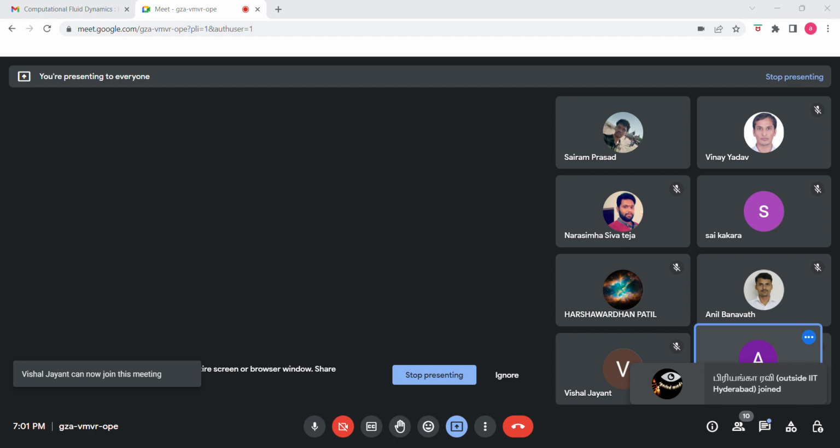Generating non-uniform grids is also not always required. But what is required is to generate an optimal grid that should be a proper compromise between accuracy and solution cost. We should see what we require in certain problems, and based on that we design a proper grid size. That is, in the discretization scheme, we go for delta x, right? That is the grid size.